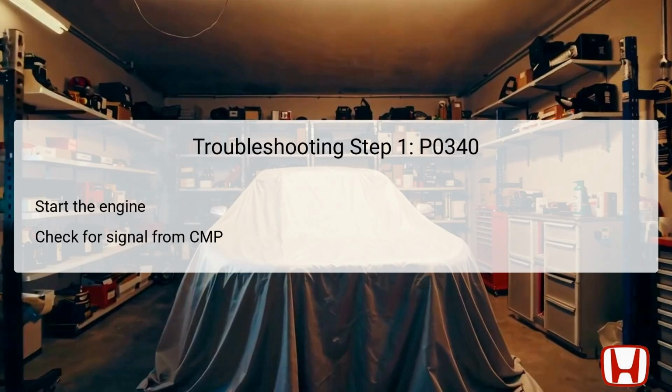The focus here is to verify whether the CMP sensor is sending any signal back to the PCM, thus allowing the technician to gauge the sensor's functionality. If no signal is detected, it indicates that further inspection of the sensor and its circuits is necessary. Hence, this step is foundational in the troubleshooting process.